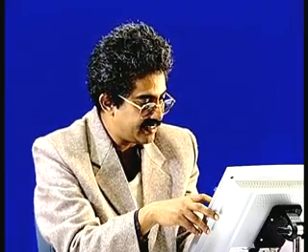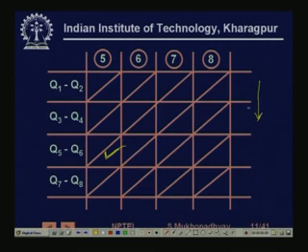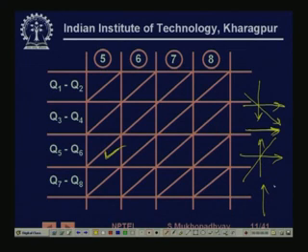Then we are changing the polarity, so we are first creating a field like this, then a field like this and like this, then only like this. So, the resultant field changes each time, and the rotor gets every time aligned with the resultant field of the two stator coils. Basically that is happening, very simple.